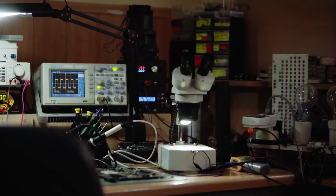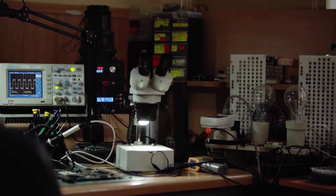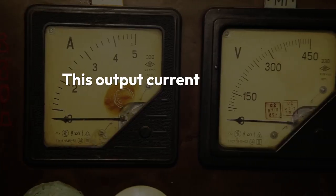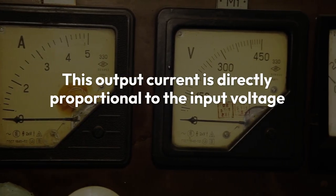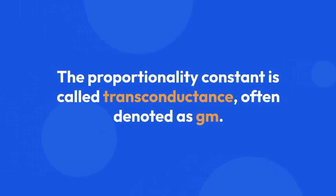You apply a voltage difference to its inputs, just like an op-amp, but its output is a current, not a voltage. This output current is directly proportional to the input voltage difference. The proportionality constant is called transconductance, often denoted as GM. Like an op-amp, an OTA also has very high input impedance, meaning it doesn't load the input signal source.